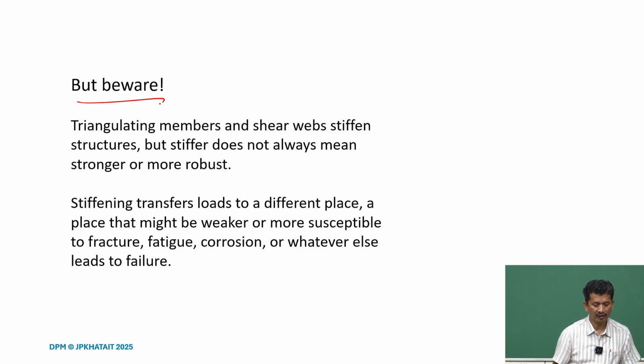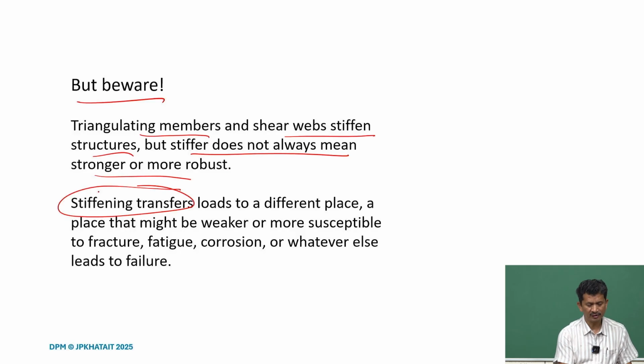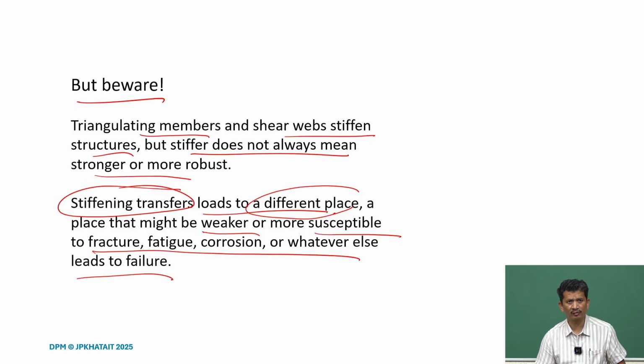But be aware, triangulation doesn't mean it will solve every purpose, right? It will definitely stiffen the structure, but it doesn't mean it is always stronger and more robust. Why? Because when we stiffen the structure, it transfers the loads to a different place, and that may be weak, or susceptible to all kinds of fracture, failure, corrosion.